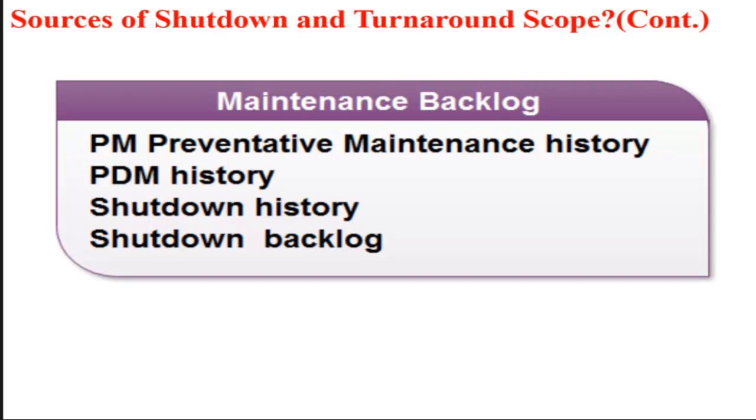Or predictive maintenance monitoring: history monitoring, vibration monitoring, oil analysis, performance monitoring, current monitoring, ultrasound, infrared thermography. All this is a PdM monitoring system, which can again create feedback that reveals a problem. This type of equipment normally reaches its engineering limits, so it is part of the source.